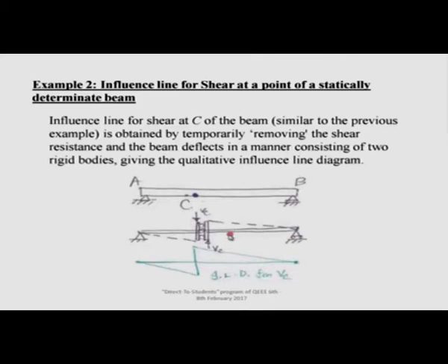Now, if I have to follow the Muller-Breslau principle, I have already applied it to the reaction of a beam, which was somewhat easier in terms of sign convention as well as in understanding the movement of the structural parts, how they displace when acted upon by forces. It was much easier with the reactions. Now, it is to be tested with the shear.